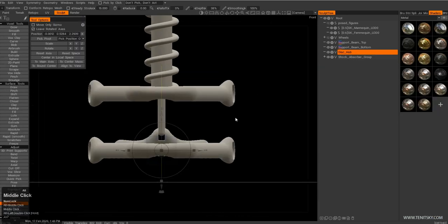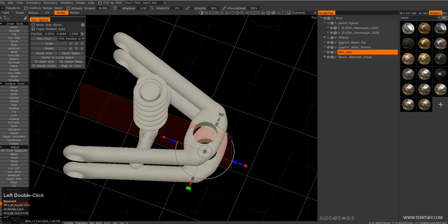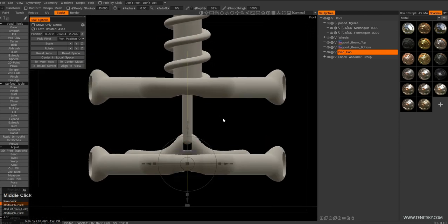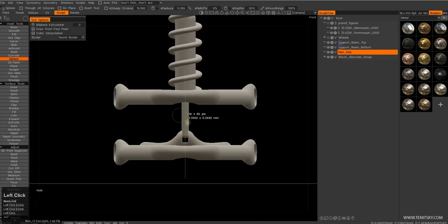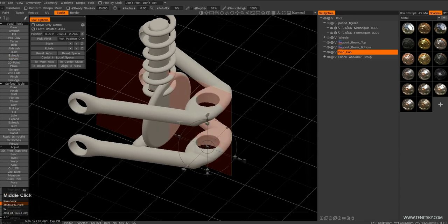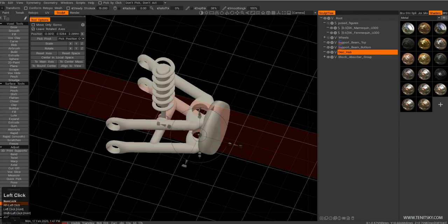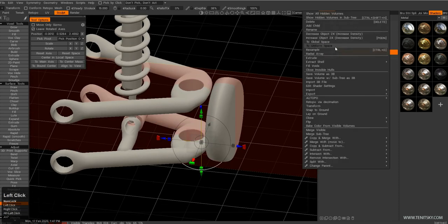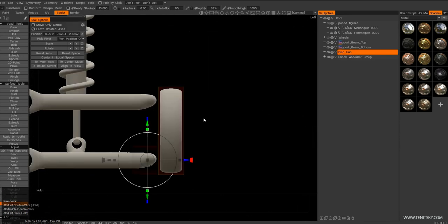So I want to create a disk for the wheel. I'll call it a disk hub, so it will contain all the connections to like support beams, then steering rod and drive shaft. So I'm using the sphere tool again. I will switch to the sphere to circle draw mode, and I'll draw it here. So carry it across and make it thicker, and now it's not a uniform bit. To fix that, I need to go and say to uniform space, and now we have our main bit right there.